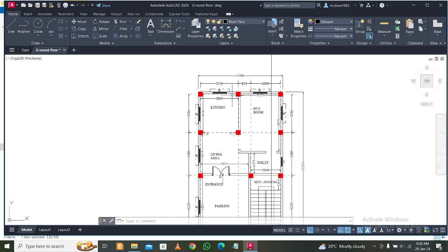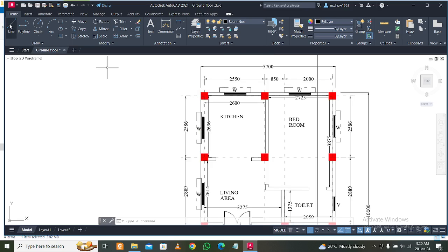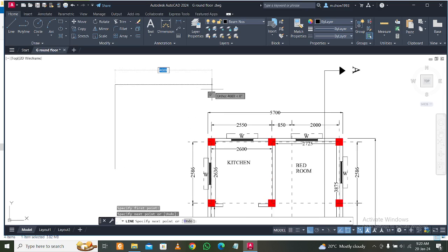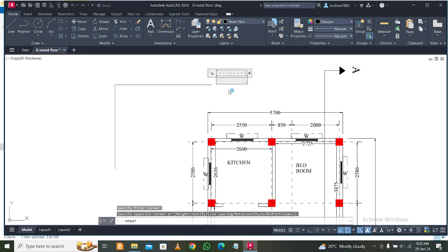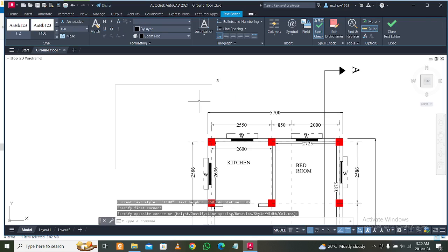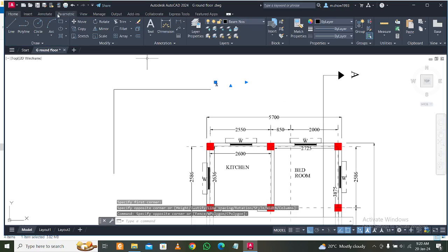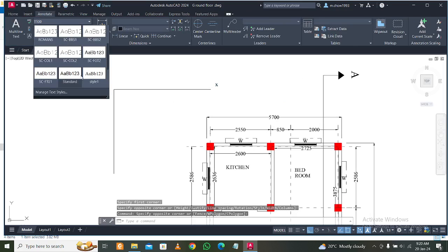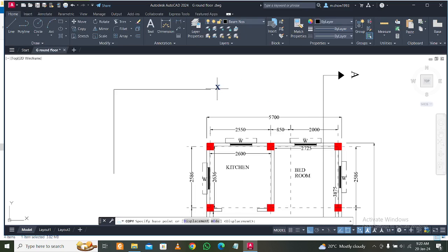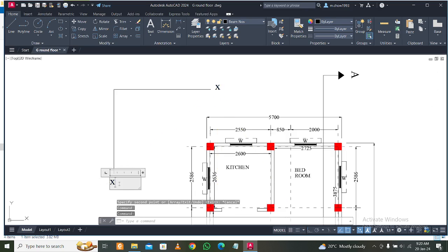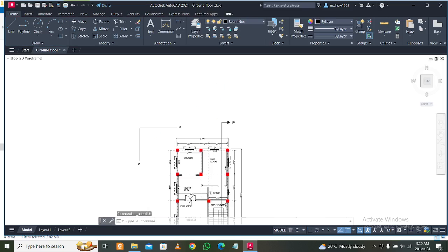So first of all, what we do is we do the coordinates. If you just see the top view in STAAD, you can see in the x-axis, if you just look into the top view, the positive x-axis is this one. And if I can increase the text size here to like 200, then the positive z-axis is this one. So we'll do the coordinates accordingly to this. Okay, this is a positive x and positive z.